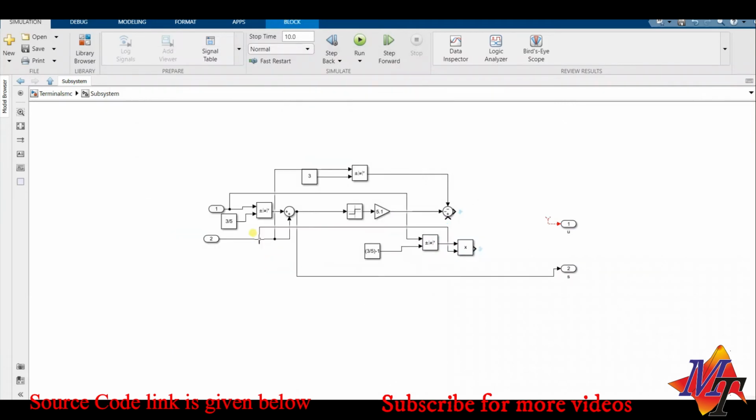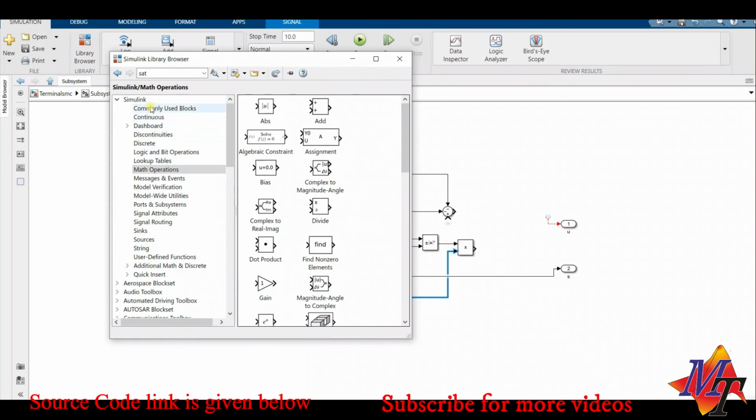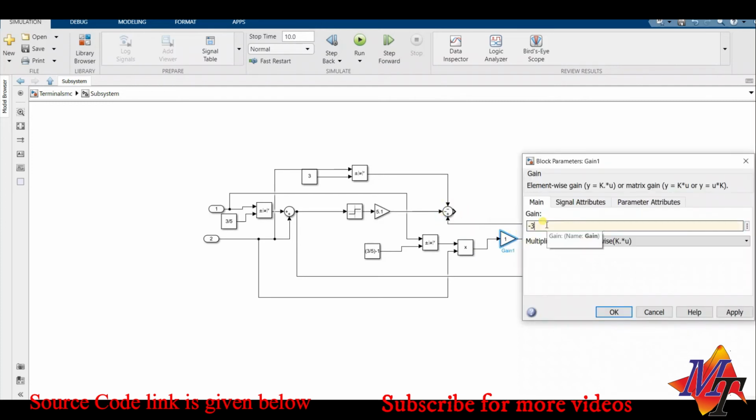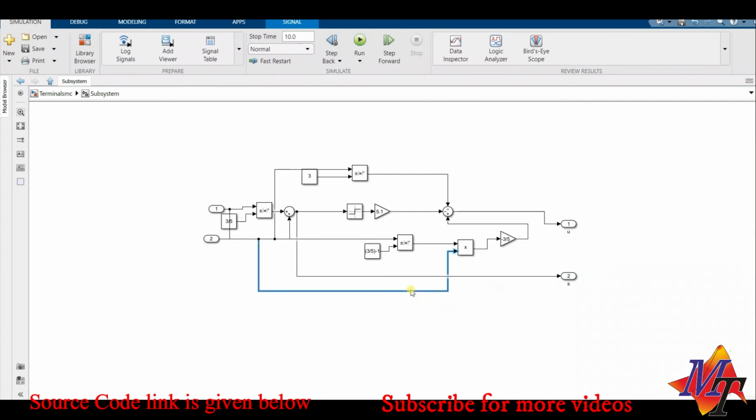So we have taken the product block here, we have got this, and we will take x2 and we will pass it through this with gain, that is minus 3 by 5 gain, and by adding all this we get the control input. So this is the Simulink diagram for basically the control input.